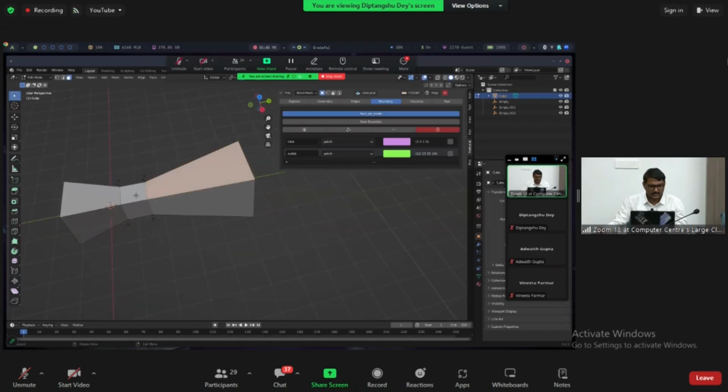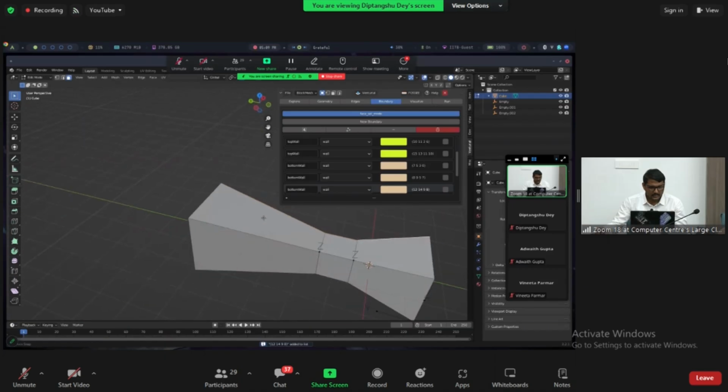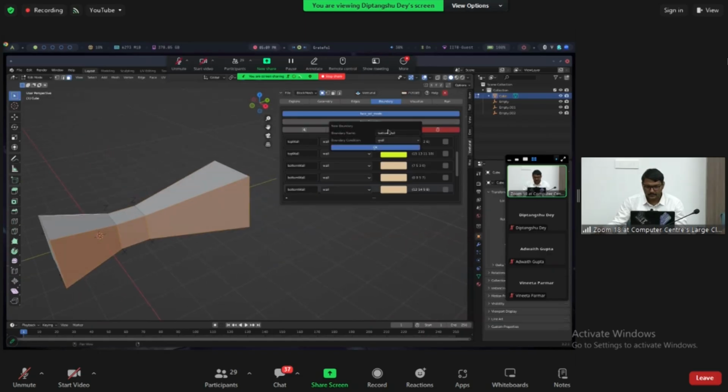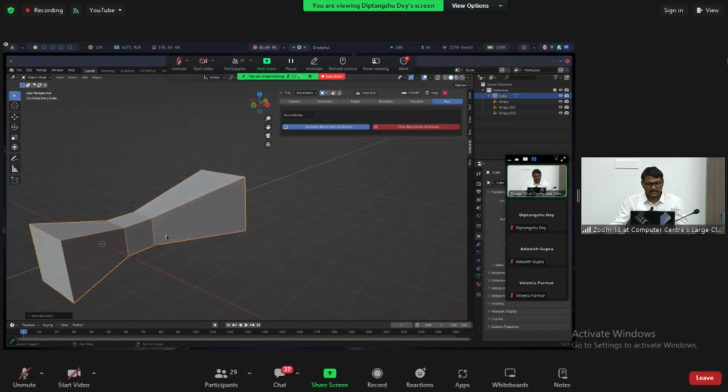So if I select these three, I can make it the top wall, which will be a type of wall. These top walls are added. I will add a bottom wall, and the rest I will list as side walls. There. So all the boundaries have been defined over here, and we can finally exit the face select mode, and now basically our mesh is ready to generate our blockMeshDict.